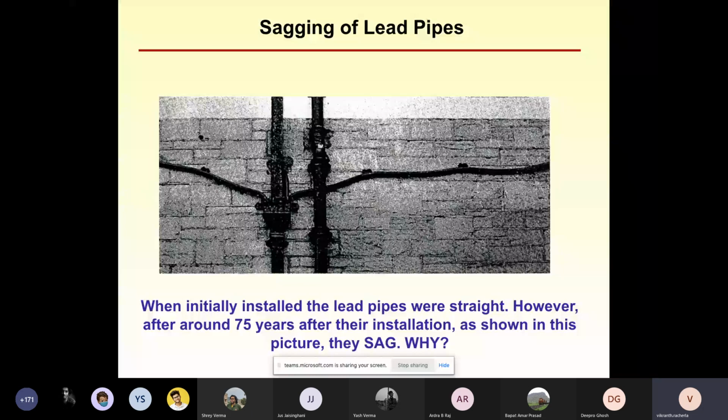These centrifugal forces, what will they do to the blades? What kind of a shape change will they cause? Elongation of the blades. They will cause them to elongate along the radial direction. And this is a problem because then the blades will rub against the outer body where you are maintaining tight tolerances. So the turbine blades are one application where you are really concerned about creep.